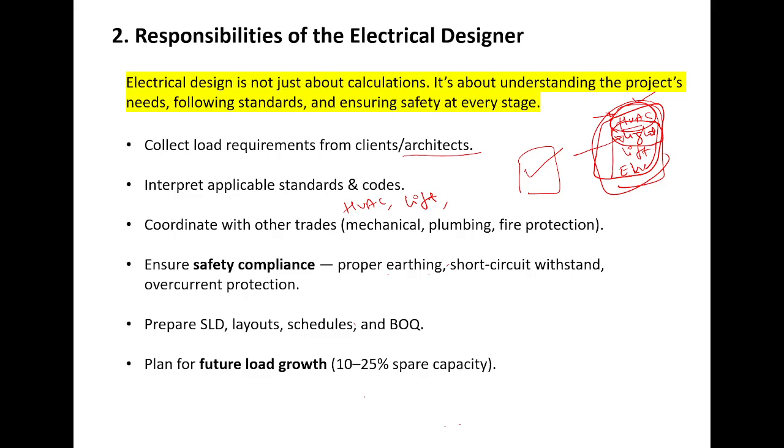Okay. Now, after this, ensure safety compliance, which means you should provide proper earthing. You should calculate proper short circuit current in your system, and use an appropriate protective device to protect your system from short circuit or overload condition. Okay. And then you should be responsible for preparing SLDs, layouts, schedules, and BOQs.